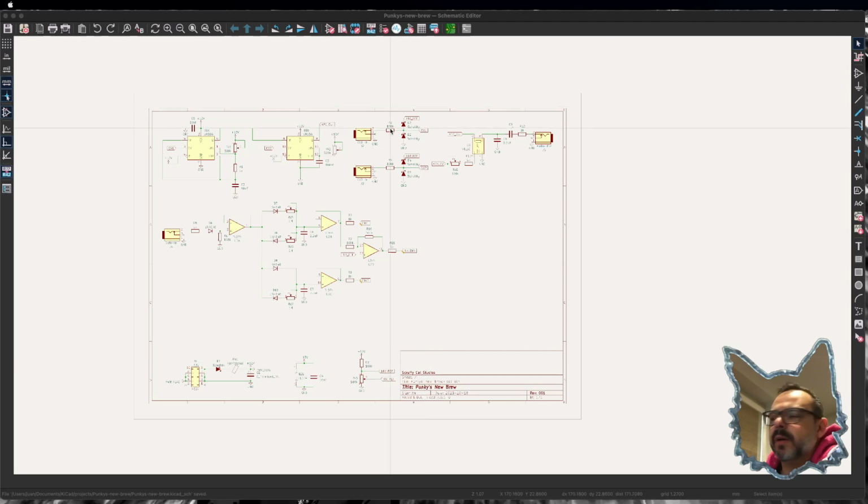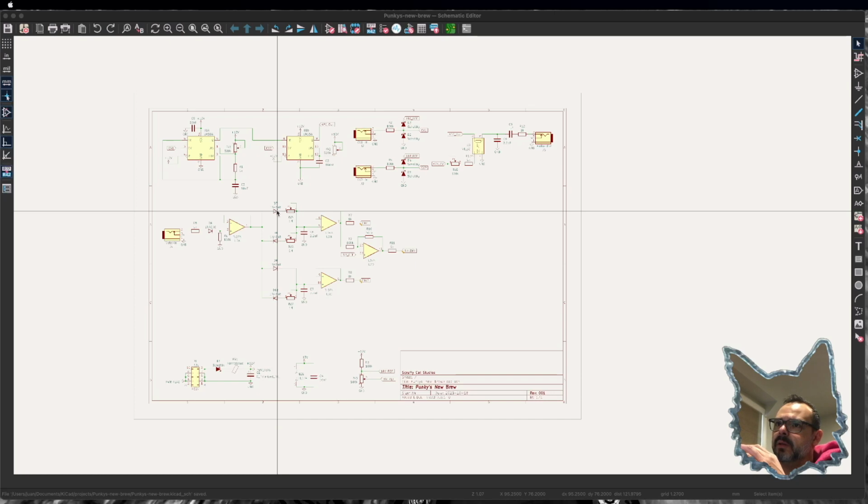By the way, if you cannot find Schottky diodes, you can easily replace them with the 1N4148. The 1N4148 are silicon diodes, and they have a larger voltage drop. Like most diodes, it's about 0.6 or 0.7 volts, while the Schottky ones are usually around, no, sorry, 0.3 volts, I believe.